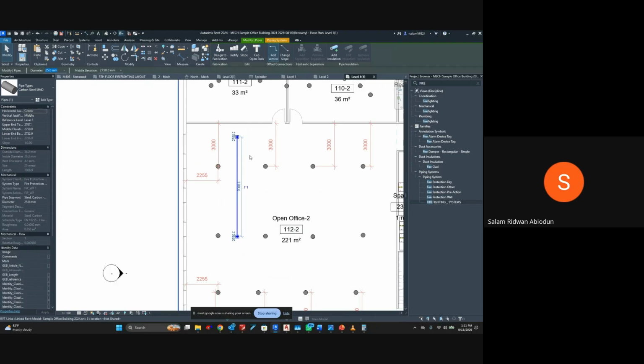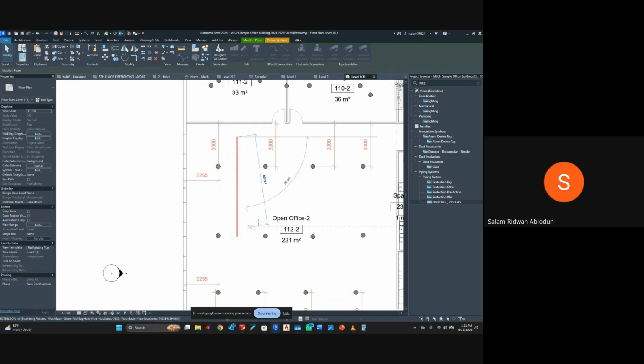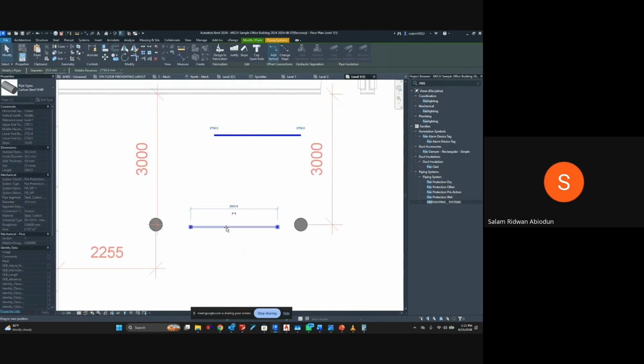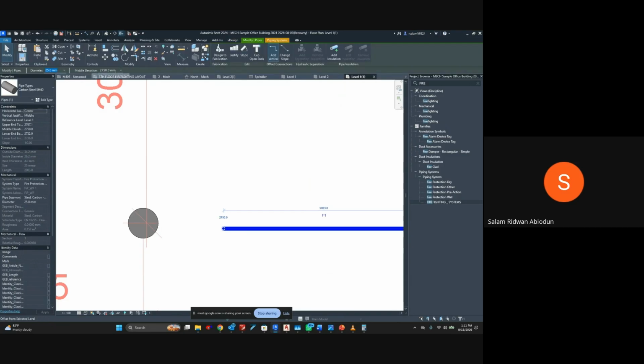Don't forget my schedule. I said from one to two sprinklers, you connect with 25 mm. When it's reaching three, you use 32. It's a pipe schedule system. So now, what is the elevation? This one is at 7,000.